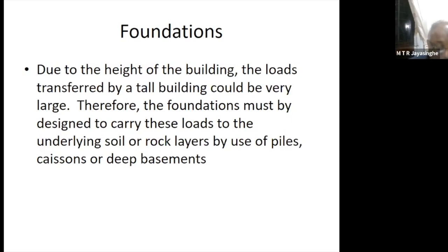That type of systems, we have developed a method of making use of pile rafts, but for that you need laterite soil available in Sri Lanka. So if you have a location high, not a low-lying land, not a land full of peat, it's a good land. You get laterite soil. The bedrock is 20 meters below, but it's laterite soils. Then you can consider using pile rafts.